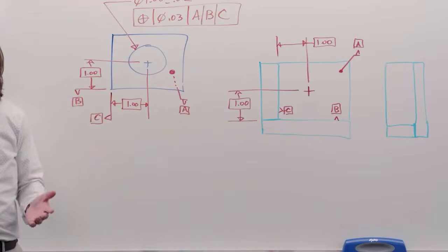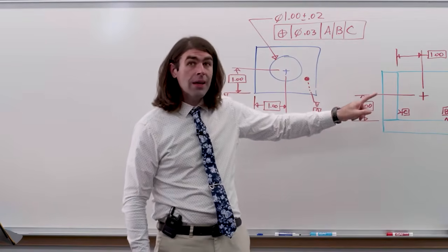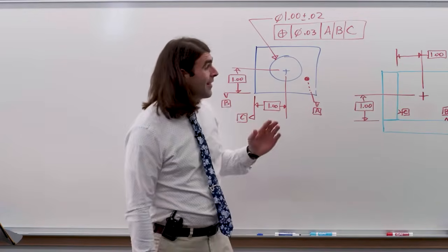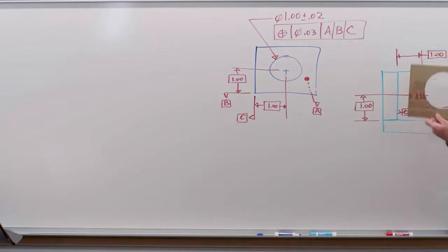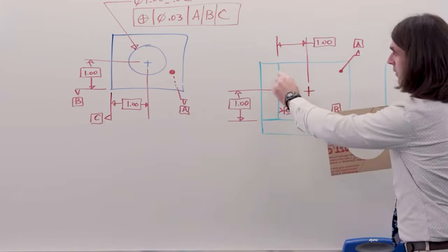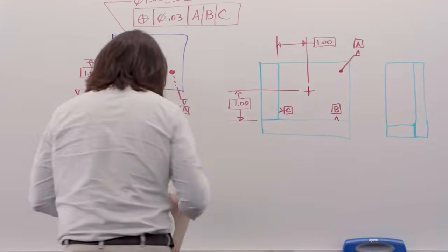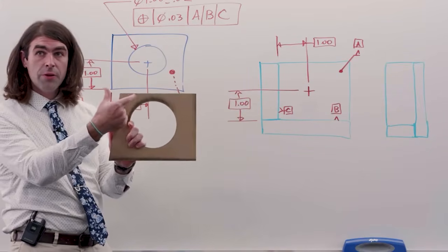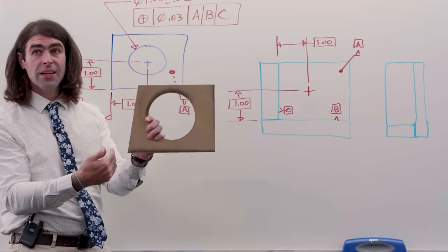So imagine you just take three perfect blocks and stick them together. So you have a nice 90-degree corner here, and you've got your datum simulators, places to measure from. Now, the idea with this setup is that you're going to put the part in there and be able to measure from these surfaces, not from the actual part surface. The reason is that if the part comes out like this, it matters whether you measure from right here or you measure from this 90 degrees here, right?